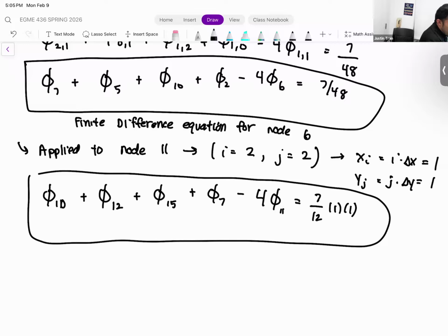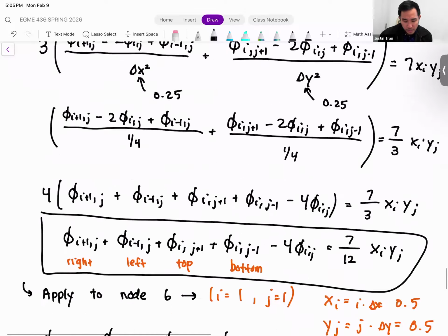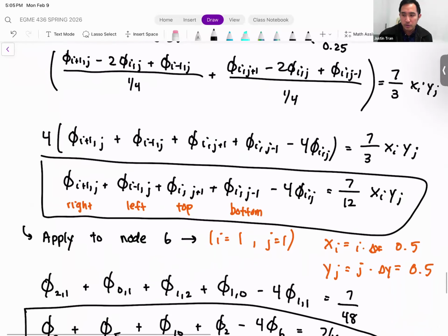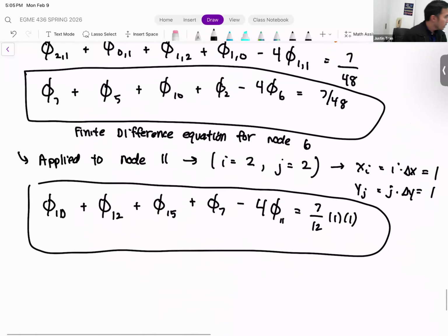So again, when you're doing these problems, it's useful to know the ID equation and the ij coordinates, all that stuff. You need that if you're going to be doing the programming, and you need that to set up some things in OpenFOAM. But for these problems, I think the easier way is to look visually at your grid, see who your neighbors are, and then just write those into the equations. That's the fast and easy way to do that. Any questions on this example here?